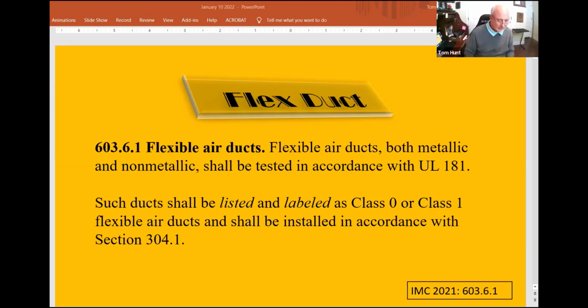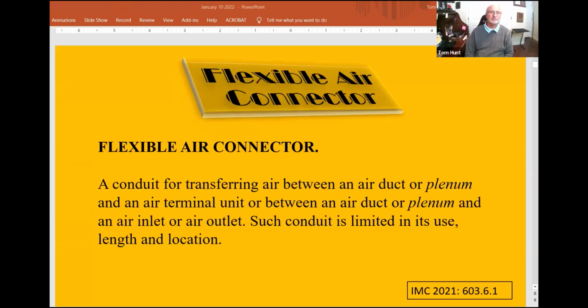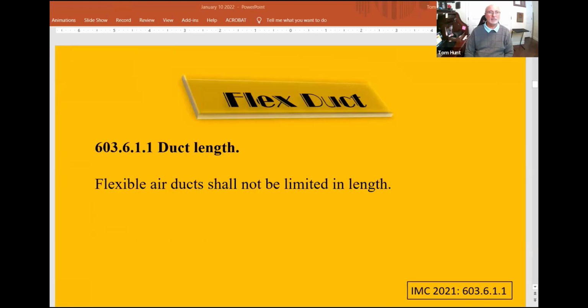So if a contractor goes into his distributor and asks for Flex Duct, is he assured that he's getting Flex Duct or Flex Duct connectors? That's going to be based on the knowledge of the salesperson at the counter, Tom. To be honest with you, I don't think distributors prevalently stock Flex connector. I think it's an order per job, because it's more geared toward commercial settings. When you walk up to the counter and say you want some Flex Duct, they're going to give you your standard Flex Duct with the liner, the insulation and the full sleeve on it. Gotcha.